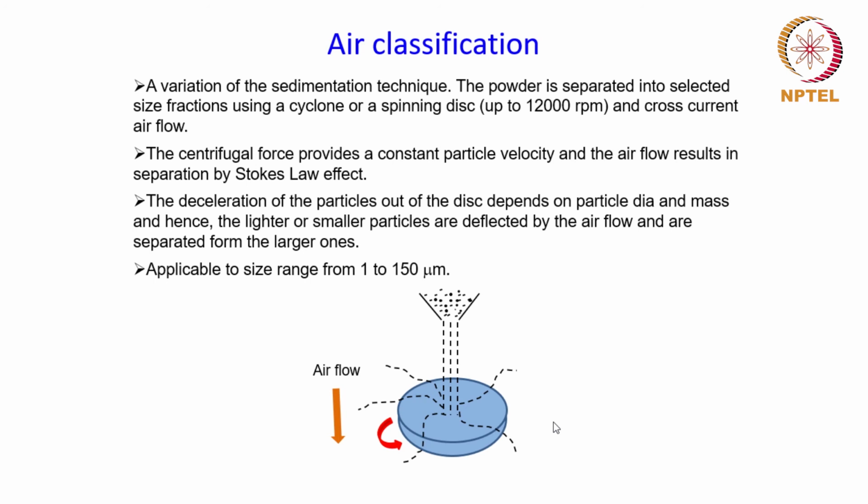The centrifugal force due to the rotation of the disc will provide a constant particle velocity, and the airflow will result in separation by Stokes law effect.